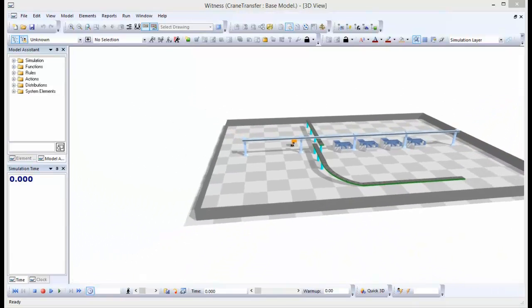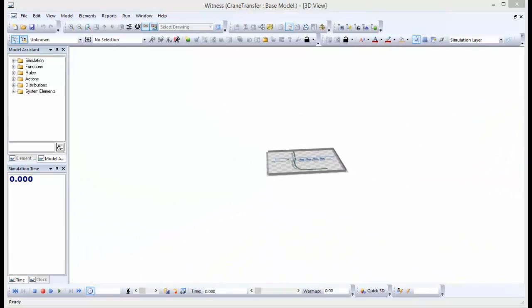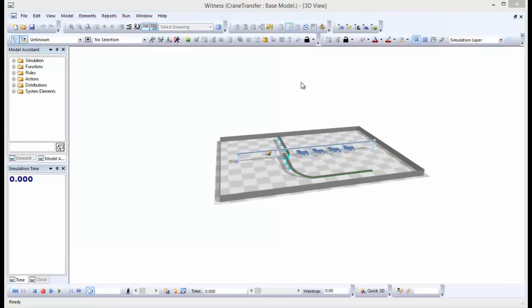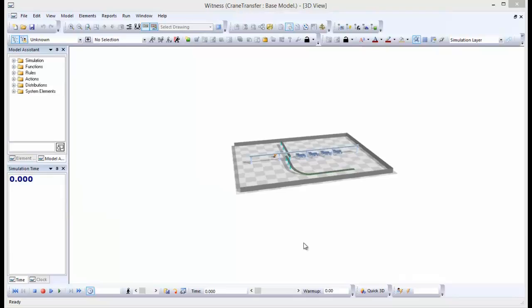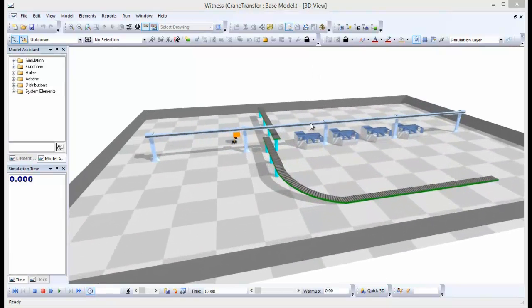Now finally in this tutorial I'm going to zoom out a very, very long way away, and sometimes we get a very, very large model that we're trying to navigate. When we're zooming in it can be very, very slow. If I hit the plus key many times, it speeds up the flight, and obviously we can halt it where we want to, but it's changed the granularity of the responsiveness of the mouse to make it easier to fly in and out of a much larger view. Keep pressing the plus key, or press the minus key to decrease the sensitivity of that mouse flight.